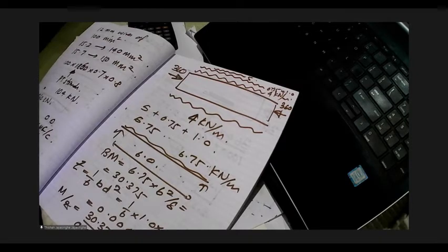So basically by going for PT, you can reduce the amount of concrete and make the structure lightweight. If it's a multi-story scenario, the total dead weight of the structure is less. So you need less concrete and less reinforcement. There's a particular advantage in going for PT in construction. By going for pre-stressed concrete, we can reduce the amount of concrete, the weight of the structure, and the amount of steel going into the structure. And in the opposite direction, we provide nominal reinforcement, that is the minimum reinforcement.